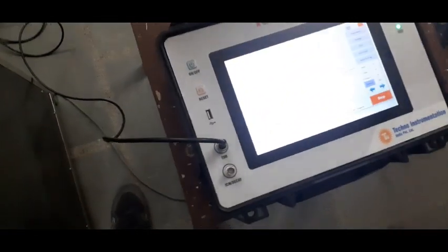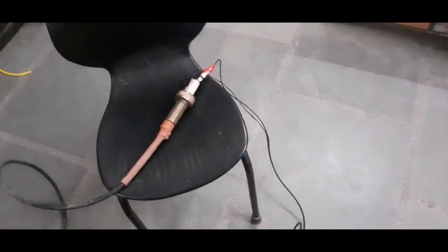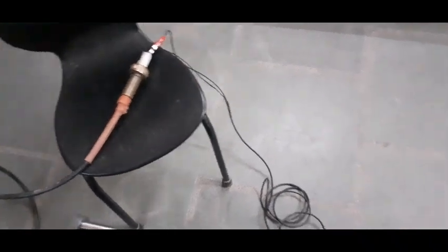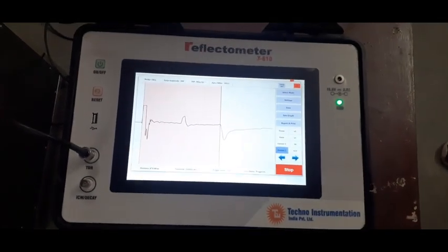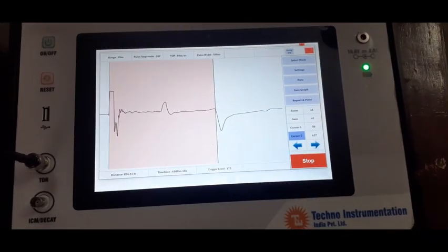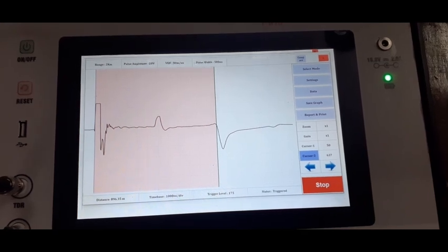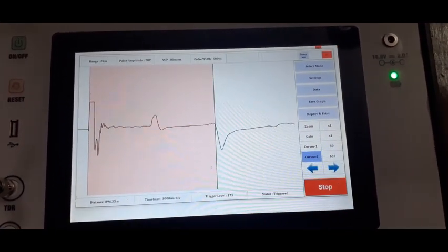We are using only high voltage cable of your surge unit to connect our TDR to the under test cable. So like this you will be able to know the distance of direct contact fault in pulse method.